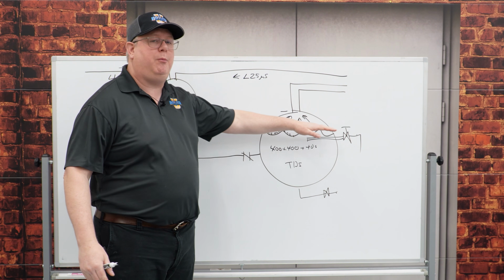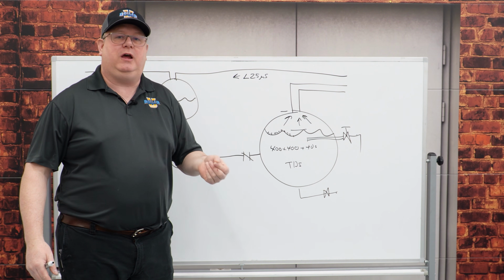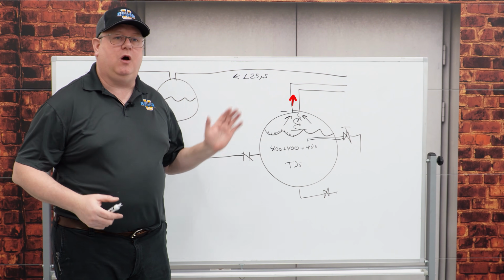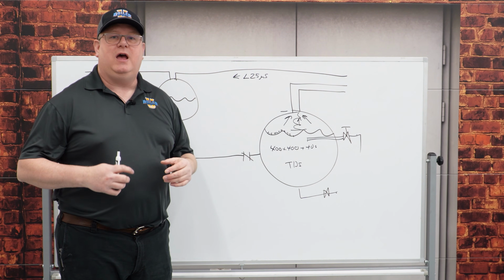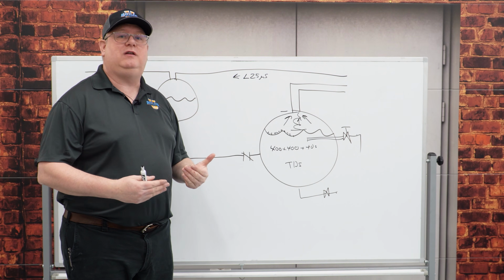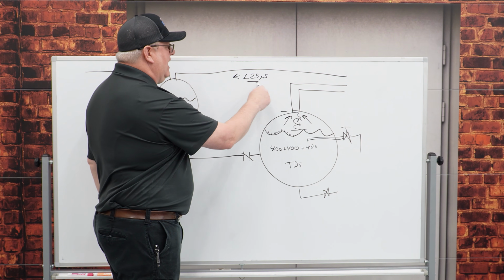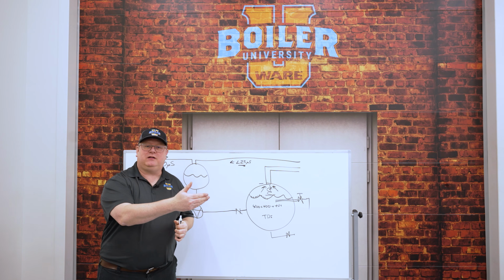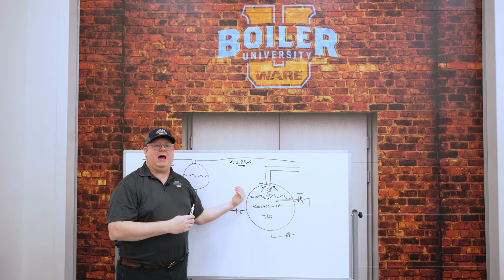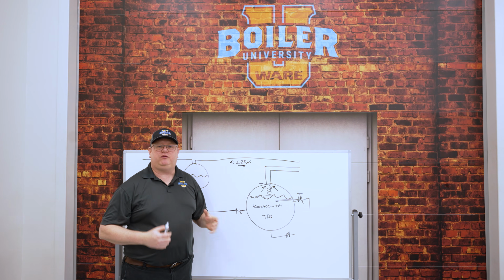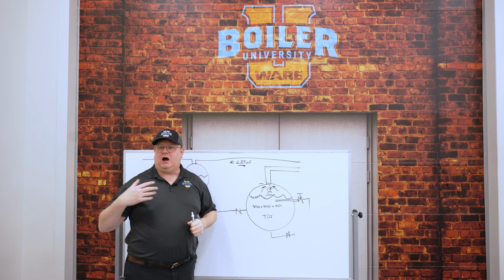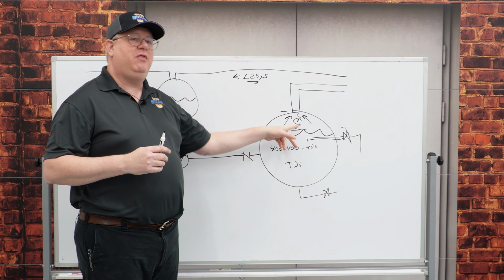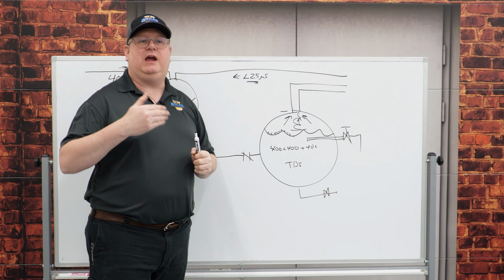If those bubbles don't pop promptly, we'll actually get a vortex of water and foam going out into the steam system. And a really easy way to test for that is to test that condensate return. Because if we're carrying solids out, that's going to be coming back. So getting a sample from a drip leg or a condensate receiver out in the system, if we see that number spike, that's going to indicate that we have carryover.